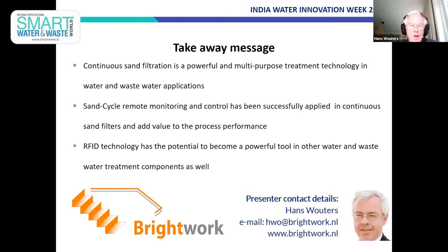in an activated sludge plant or an MBBR or whatever, and then the system can be used very effectively as a polishing step to create very low levels of nitrate, of nitrogen and phosphorus, and also it can be then very effective to reuse the water for all kinds of purposes. So see it as a final stage of a municipal wastewater treatment works as a stepping stone towards water reuse.